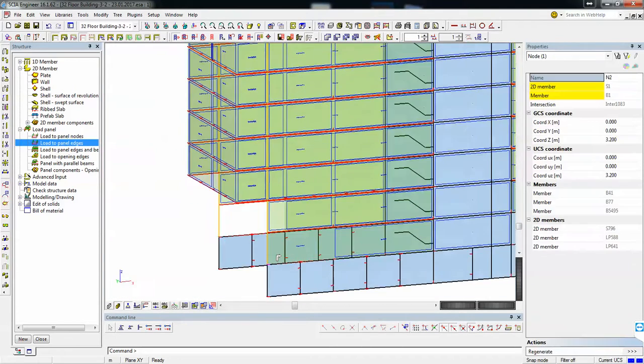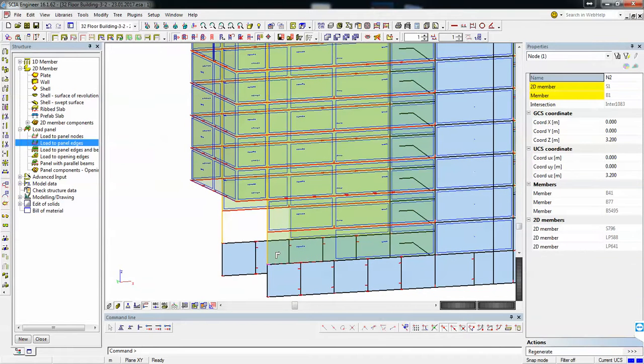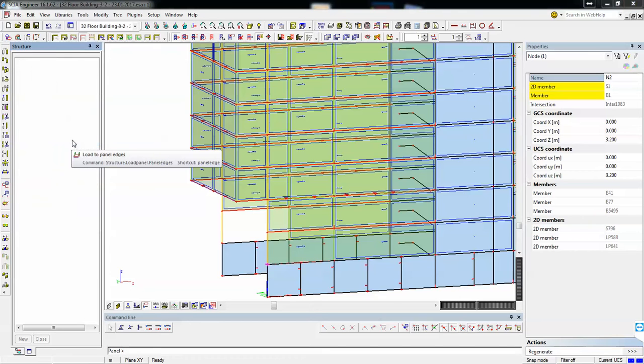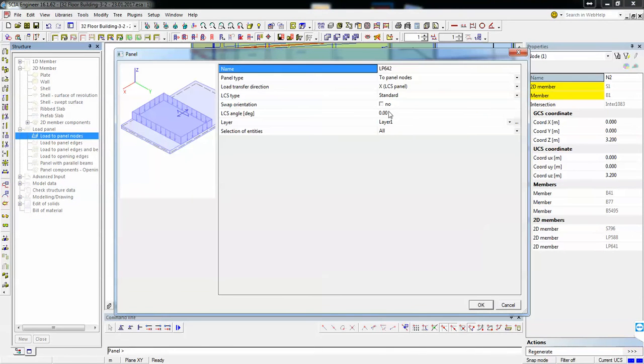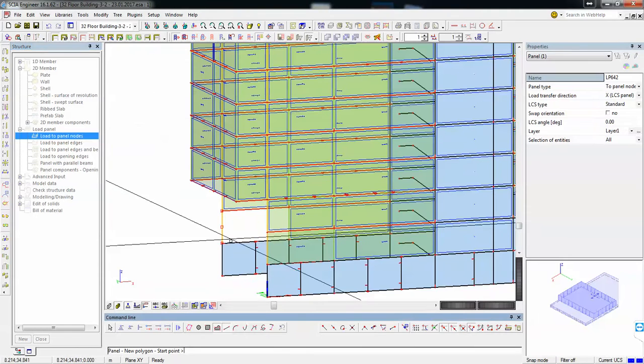However, I have to enclose the building in order to use the 3D generator, otherwise it won't generate the wind. So this is a method from Eurocode, but it is dependent on a closed structure. So this is why I need to do a fully enclosed model of your structure with panels or walls.